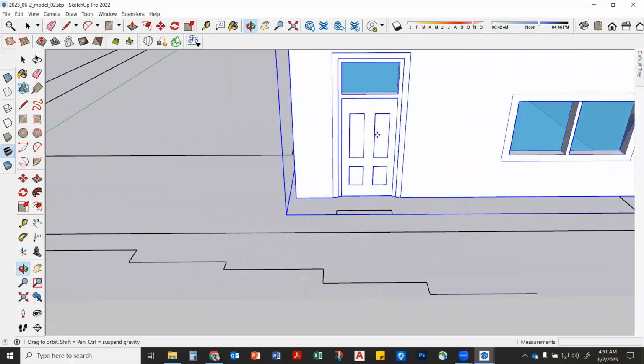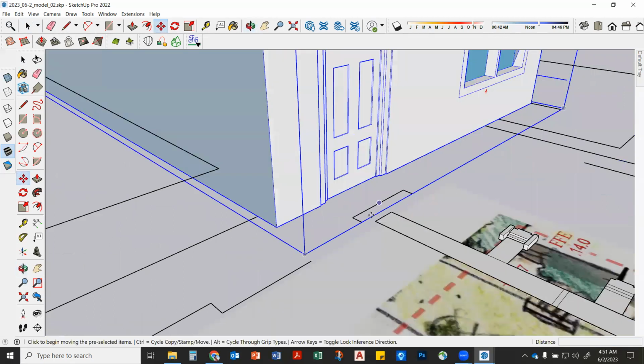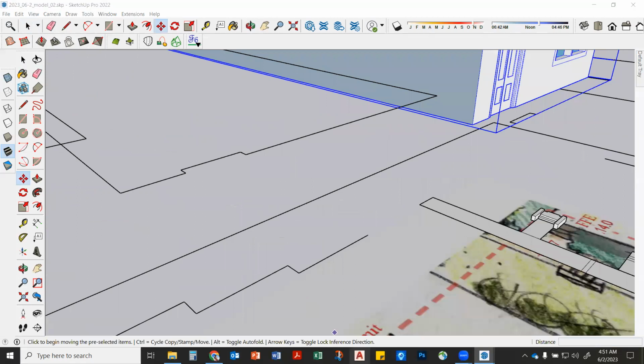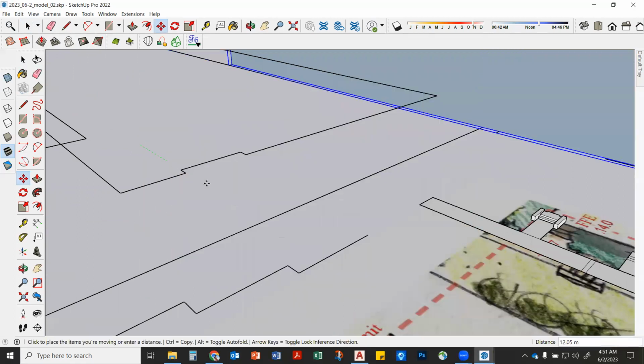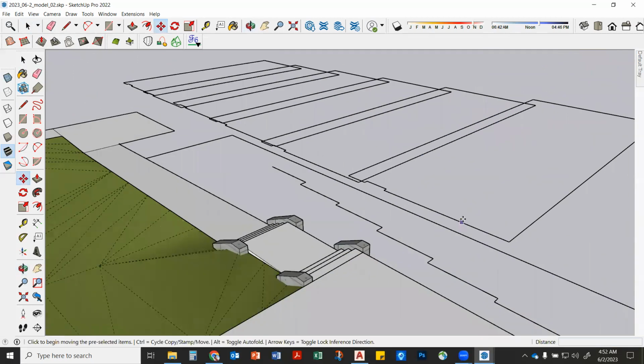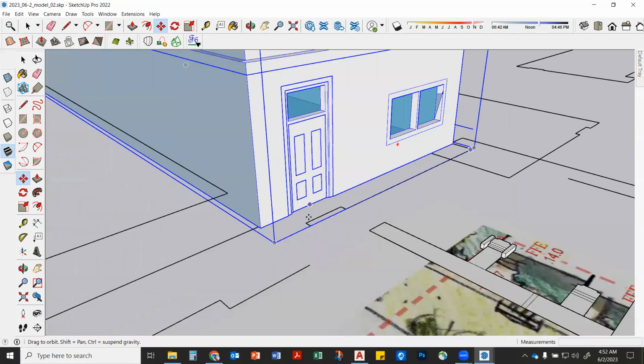Okay, but follow me on this. Keep watching. What we're going to do is I want you to line up. So then I need this thing to line up. See, that's where the door is, right? On every one of these CAD blocks, when I was in CAD, let me open my CAD as well. When I was in CAD, I drafted one of these buildings, right? And then I made a block out of it, and then I just copied that block. So these blocks, once you bring a block from AutoCAD into SketchUp, it becomes a component, okay? And that's very cool because of this thing that we're going to do right here, okay?